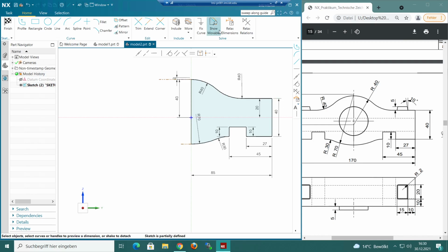Probably I'd say relax relations is enough often if you want to change something, but if you use one of these two functions, then do like I did right now, and afterwards always check what has been changed and if that messed up what you actually want. Like right now, where it messed up these two dimensions. The rest still looks perfect to me, I would say.